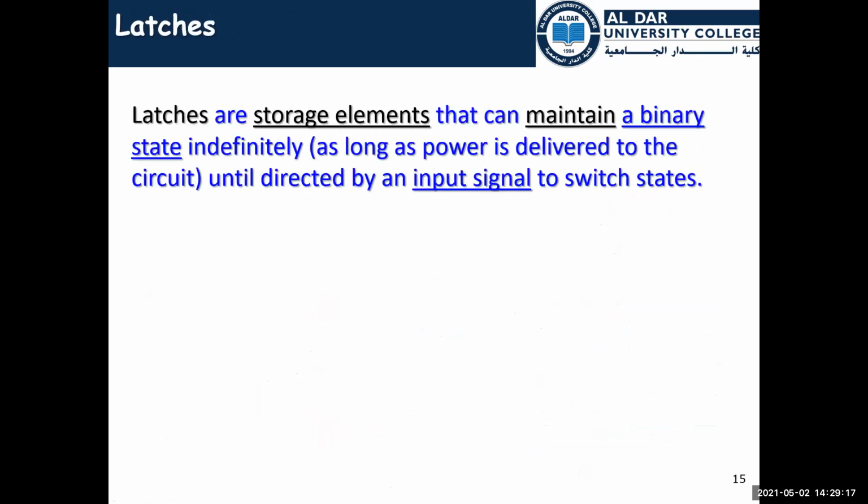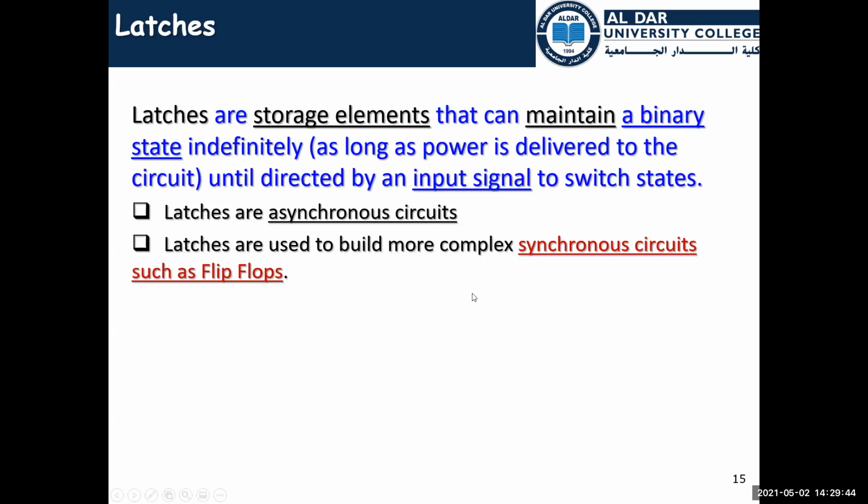Latches are storage elements that can maintain a binary state indefinitely, as long as power is delivered to the circuit. This means we have the first storage element, which is the latch. The latch can hold data for a specific time. Latches are asynchronous circuits. Asynchronous means that they don't have a global clock that can control them. Latches are used to build more complex synchronous circuits, such as flip-flops.